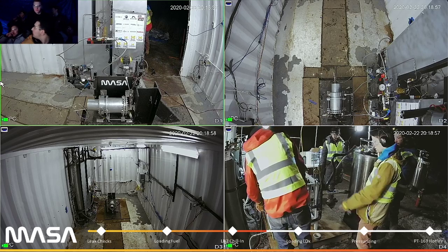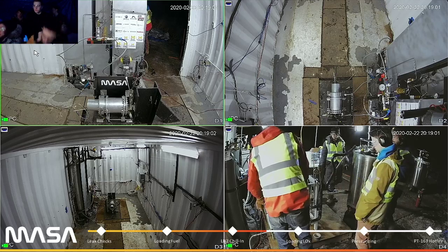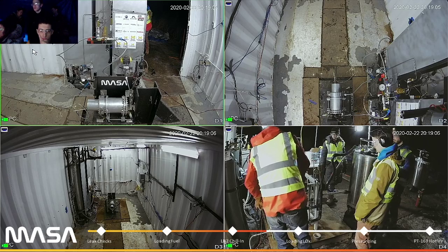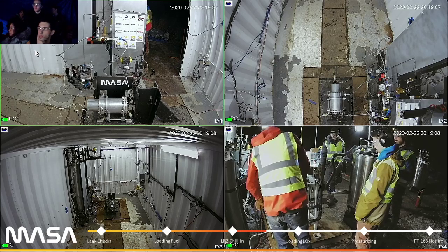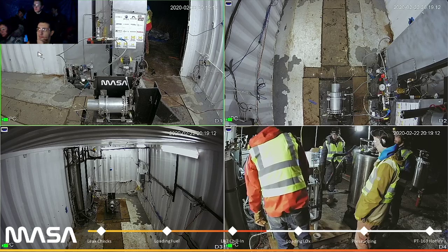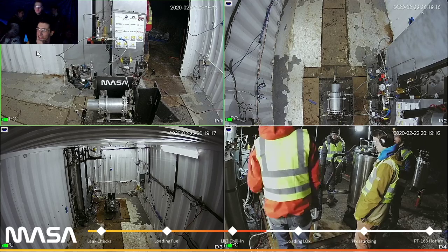We'll wait for fluid out the dip tube. Once fluid comes out of the dip tube, we know the tank is full. We'll stop filling. Then we will pressurize fuel. Once fuel is pressurized, we will re-top off LOX, so just get a tiny bit more fluid in the tank. And then after that, we basically just press up LOX and then move it.